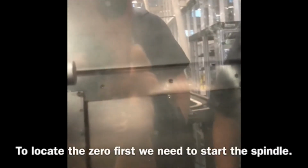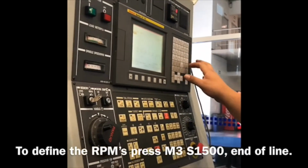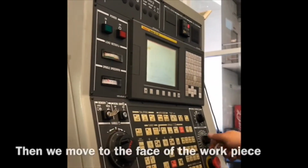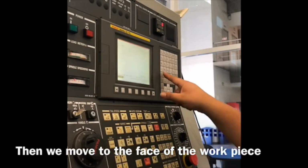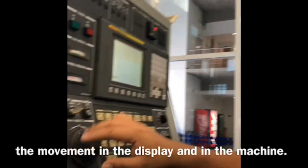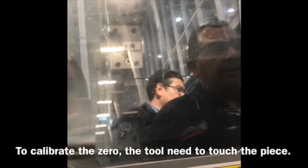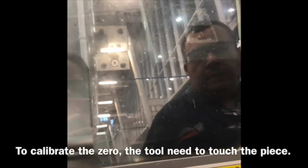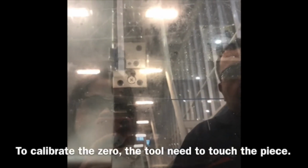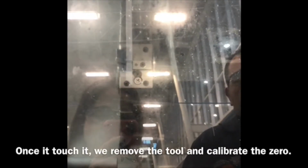To locate the zero, first we need to start the spindle. To define the RPMs, press M3 S1500, end of line. Press insert and run. Then we move to the face of the workpiece manually. When we are doing this, we can observe the movement in the display and in the machine. To calibrate the zero, the tool needs to touch the piece. Once it touches it, we remove the tool and calibrate the zero.